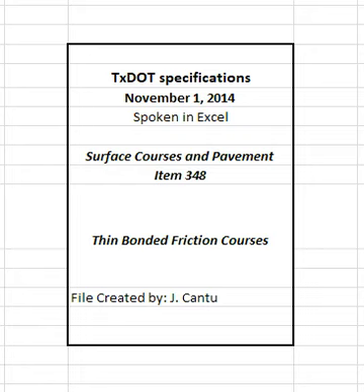5.2.1 Target percentage. The JMF target asphalt percentage will be used to calculate the weight of asphalt binder unless the measured asphalt binder percentage is more than 0.3 percentage points below the JMF target asphalt percentage or less than the minimum percentage specified in Table 8. Volume truck meter readings will be adjusted to 140 degrees Fahrenheit and converted to weight.